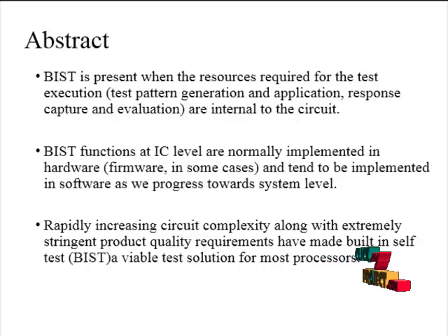In the 14nm Intel SoC, a reusable BIST engine called Converged Pattern Generator Checker (CPGC) is architected to detect memory and input-output defects, and combined with software-assisted repair technology to automatically repair memory cells. The memory cell defects are on 3D stacked wide input-output DRAM. Additionally, we also present the CPGC gate count, power, simulation and silicon results.